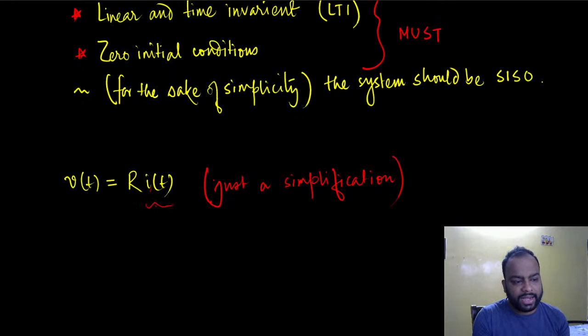So if this current is an alternating current, for example, if you increase the frequency, you will see the resistance is increasing. This is called the skin effect. Okay, so you might have studied this in power systems engineering, right? So if you provide high enough frequency, the electrons tend to move towards the outer shell of the conductor. Okay, and nothing really flows to the inner core of the conductor. There are so many things that happen in a simple conductor. Okay, and this is really not the Ohm's law.